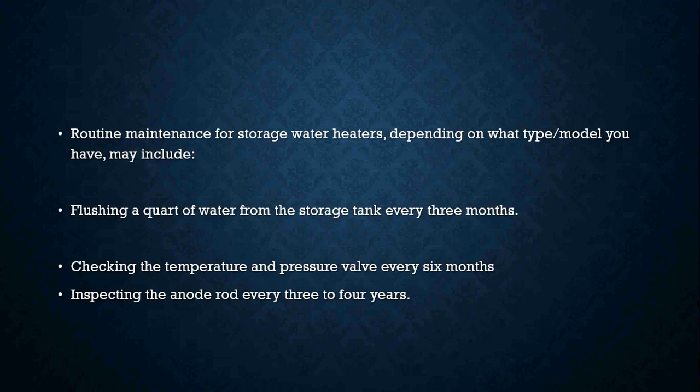Okay, some routine maintenance will actually require you to flush at least a quart of water from the storage tank every 3 months. You're going to want to check the temperature and pressure valve every 6 months. Again, this all depends on the model of your water heater.